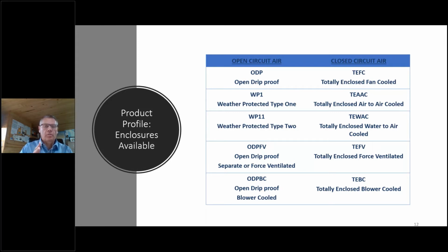The workhorse of our industry in mostly low voltage motors is TEFC, and I've used a bunch of acronyms here that we can go through. A totally enclosed fan-cooled motor is basically an enclosed motor with a shaft-mounted fan, and it pulls air from the non-drive end over the motor body through to the drive end.